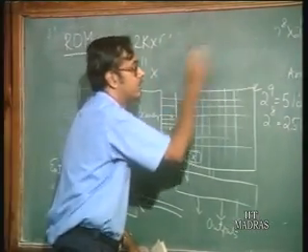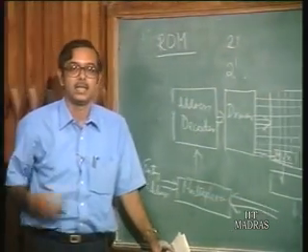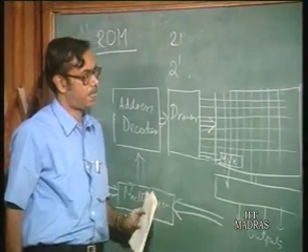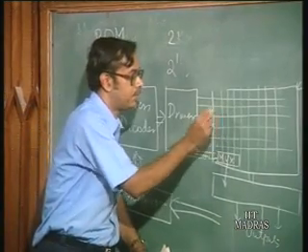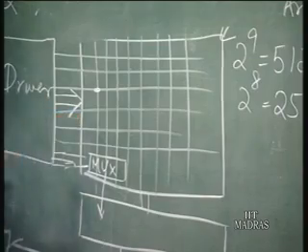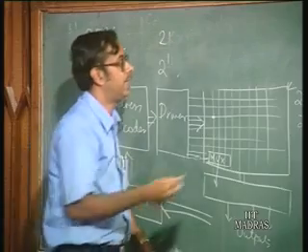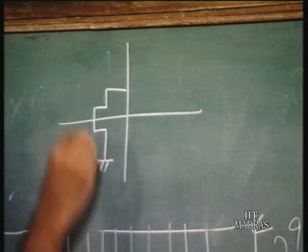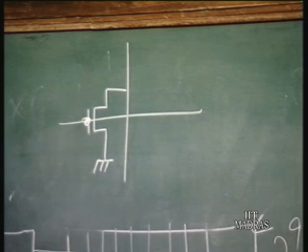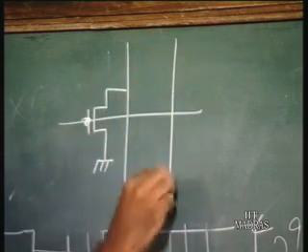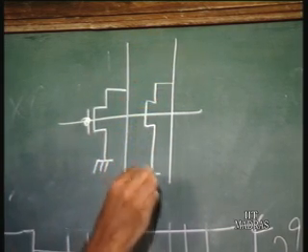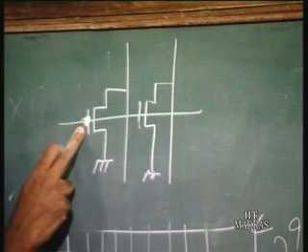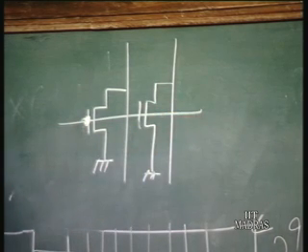Now, again we come back to the topic which we were discussing, that is, how does the bipolar transistor help in improving the speed. Basically, in this ROM, at each intersection of the rows and columns you might have a cell. So, what is the cell like? If you have an intersection here, the cell consists of a MOS transistor which is connected like this. In another location, this may not be connected. Here the gate of this MOSFET is connected to the word line.